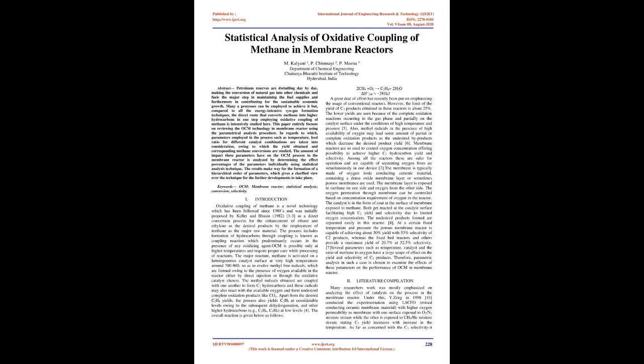A great deal of effort has recently been put into emphasizing the usage of conventional reactors. However, the limit of the yield of C2 products obtained in these reactors is about 25%. The lower yields are seen because of the complete oxidation reactions occurring in the gas phase and partially on the catalyst surface under the conditions of high temperature and pressure [5].